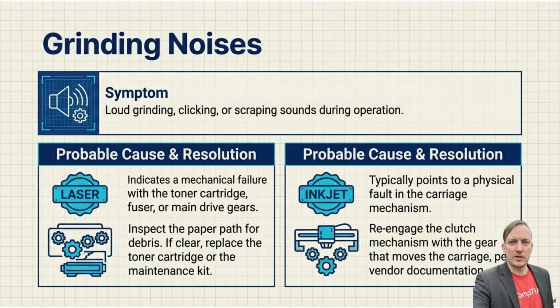In an inkjet printer, grinding typically points to a physical fault in the carriage mechanism. You may need to re-engage the clutch mechanism with the gear that moves the carriage per the vendor documentation.